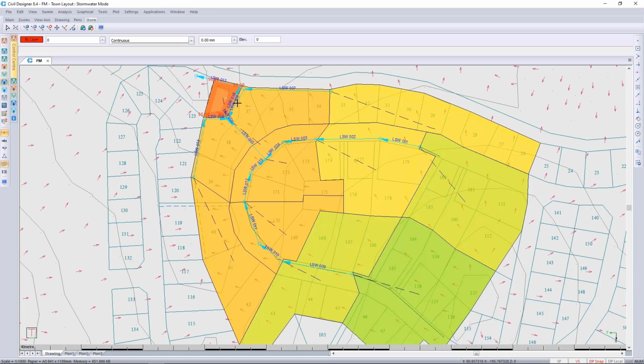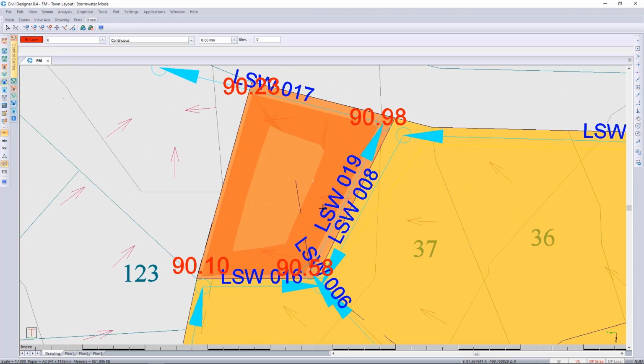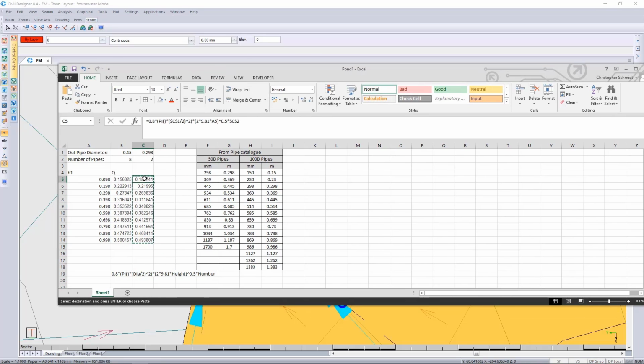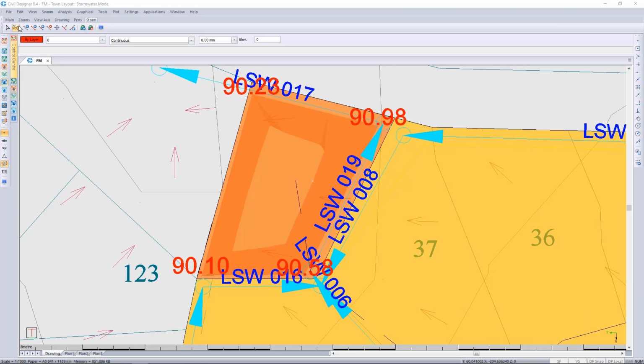One of the common errors is to undersize the pond and choose a pond size that is chosen with the throttled amount. So earlier we chose 50. That can cause issues where your outlet is far less during the lower part. So if we go to the pond here and we look at these, Q for the outflow is far less during the initial stages of the flood event, and that could cause that you need a higher storage. But you can choose in the stormwater to have an overflow.